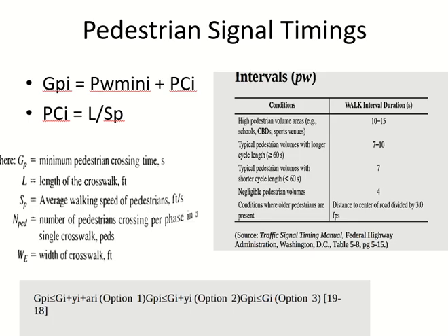After yellow, it will become all red. All red means what? This one is red, and this one is also red. Because this one is red, it's still safe for me. So theoretically, I'm safe during green, I'm safe during yellow, I'm safe during all red, because in all these three timings, these cars are not moving. The cars coming from the other side will not start moving yet.